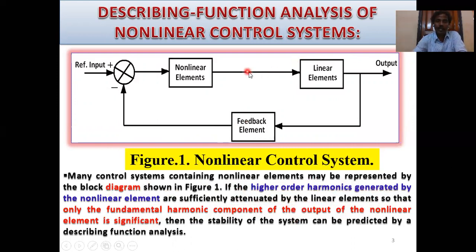That means higher order harmonics are generated by the nonlinear element and sufficiently attenuated by the filter, so only the fundamental harmonic component is significant on the output side.